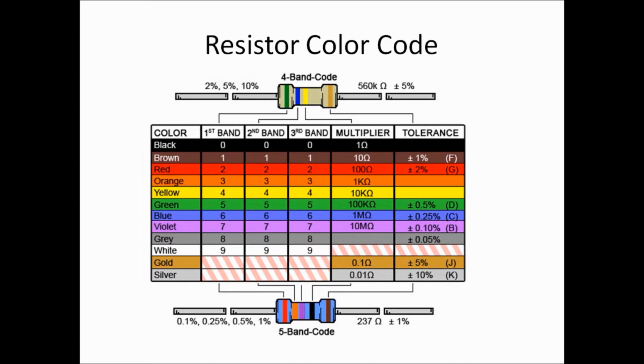Sorry about that. For me, the last band is red. My first band was brown, which is 1, then I have 0 for black, and then I multiply it. I don't have a third digit band on mine, so I go straight to the multiplier. I multiply it by 100. So 10 times 100 is 1,000. That means it's a 1,000 ohm resistor, or 1K.